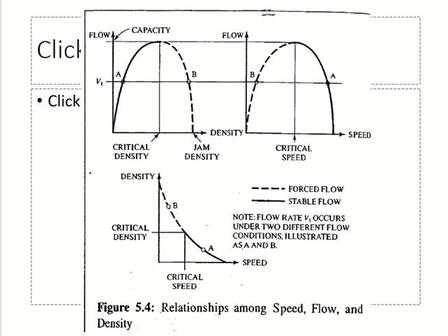Clear? Okay. When do I achieve 0 flow? 0 density. Correct? Yes, correct. When you have 0 density, you have 0 flow, right? There are no cars on the road, so no flow. But it is only half the answer. You look at the graph. Yes. Jam density is also 0 flow. Okay. So 0 speed can only happen in one condition, jam density.